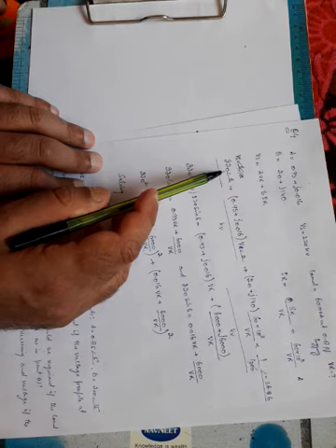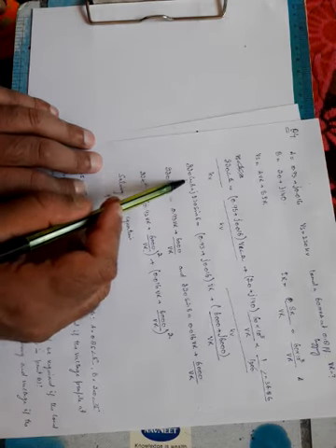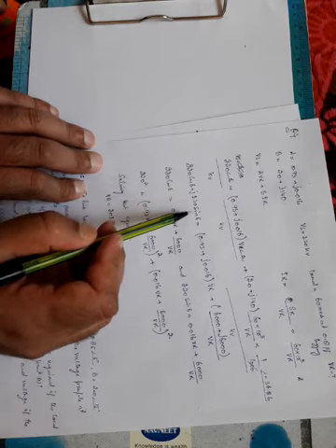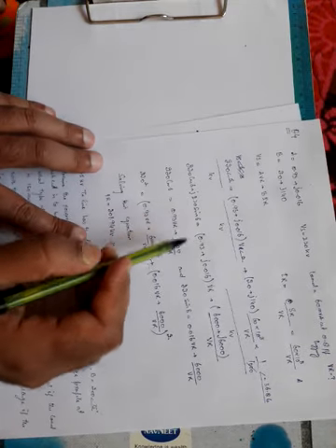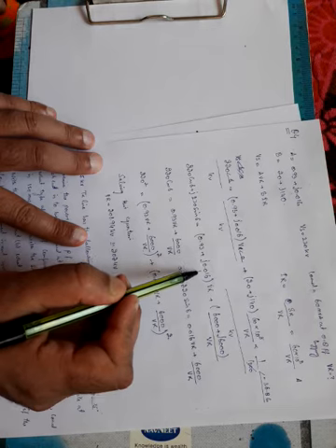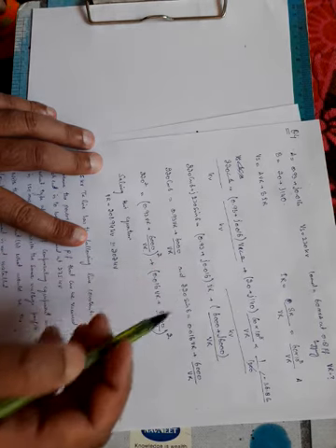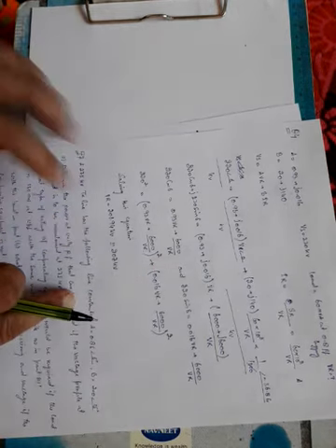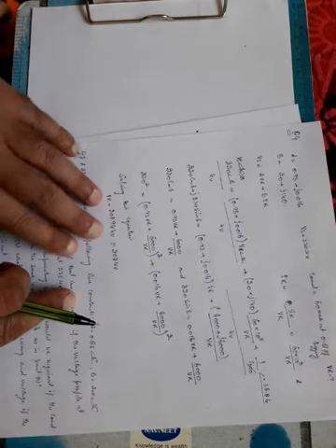I will write it down in the rectangular form. It will be equal to 220 cos delta plus j 220 sin delta plus 0.93 plus j 0.016 into VR, because VR will not have any imaginary part, its angle is 0.